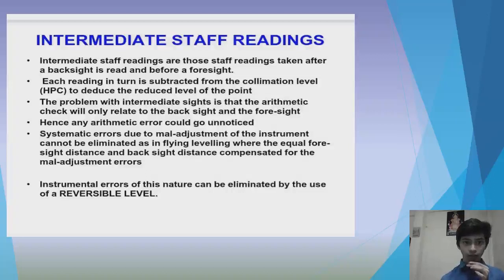Systematic errors due to maladjustment of the instrument cannot be eliminated as in flying levelling, where the equal foresight distance and backsight distance compensate for the maladjustment error. Instrumental errors of this nature can be eliminated by the use of a reversible level. Go to the next slide.